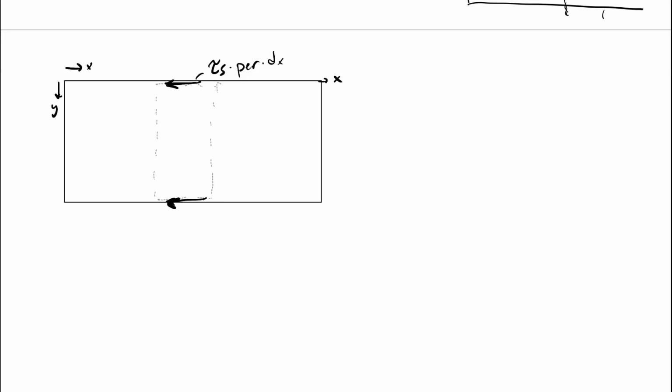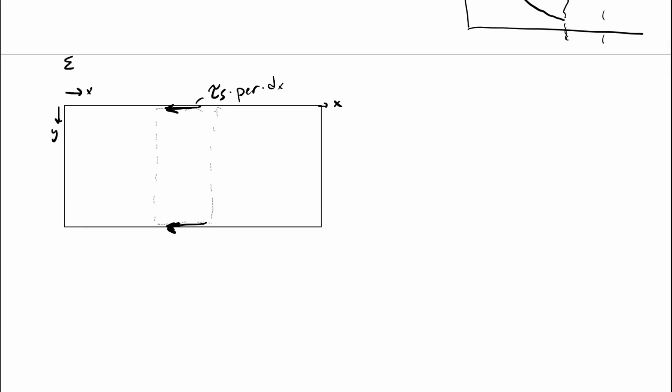Okay, so this is an x momentum balance. What are we trying to do? We're trying to take the sum of the forces in x plus x momentum in is equal to x momentum out plus any change with respect to time in x momentum. Let's do this for a steady problem, so it's not changing with time, and that goes away. And we do need to consider both forces in x and momentum in and momentum out.